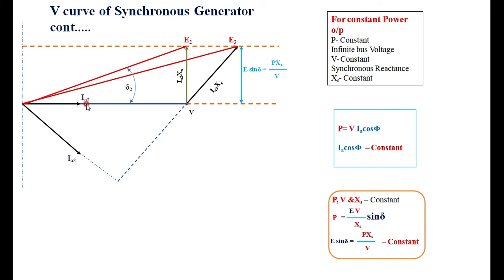That is correct. Now, what we have observed here is that the current, from the 100% excitation, that is from the unity power factor, is moving into the lagging power factor. The other observation we have seen here is that if your excitation is increasing, the generated voltage is also increasing. At the same time, the current is moving towards lagging in nature. These are the observations we are getting. That is, for over excitation, the current becomes lagging.